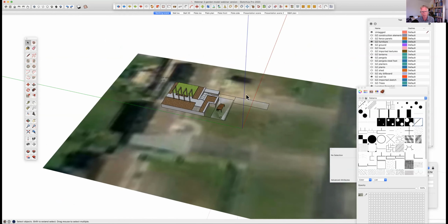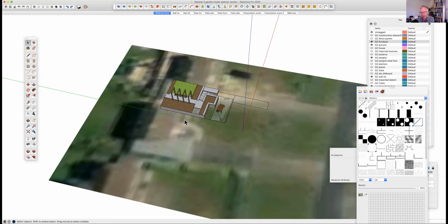And as I get towards the end of a project, I could take all my geometry and rotate it round so that the north in SketchUp was the north of my site. But then everything would be off axes, which would be frustrating because when I created geometry, it would still align to the axes, but to put it into the model, I would then have to rotate it. And I think that would drive you mad. So the alternative is to leave the geometry aligned to axes for speedy modeling and to alter the default position of north within this session of SketchUp.